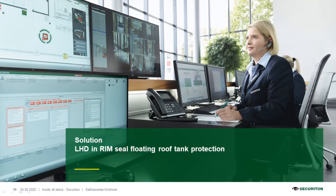It is possible. And what is the suggestion on the type of tube used for a floating roof tank? Is it copper or stainless steel? Both are possible, but in most of the countries and requirements, they prefer to use stainless steel because of robustness and also cleanliness, as well as to maintain the cable, the detection system is better. So it's always recommended to use stainless steel. So we don't have any further questions, so you may continue. Perfect. Thank you so much. I'll continue with the solution.